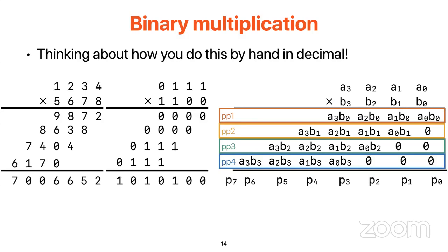If you remember how we deal with the sequential adder, we are not too greedy, right? Every cycle we just generate the result for a bit. And similarly, for the binary multiplication, we are not too greedy in a way that every cycle we just gradually build up the partial result, or say the half-baked result of the multiplication.